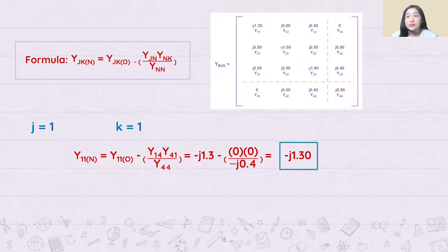Next stop. So basically, we are just going to solve for 6 values. Pero bakit meron tayong 9 values dito sa ating matrix, right? Tingnan mo, meron tayong 9 values here but we are only going to solve for 6. So how is that so? Diba sabi natin, itong diagonal, they are different from one another. Different yung values nila, so we have 3 na. So bakit 3 na lang kailangan natin hanapin? Because sabi natin, Y12 is equivalent to Y21, and Y23 is equivalent to Y32, and Y13 is equivalent to Y31. So that's 3 values na lang hahanapin plus 3 from our diagonal coefficients. So that would be only 6.